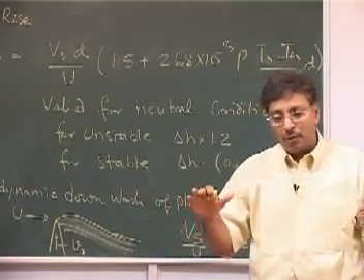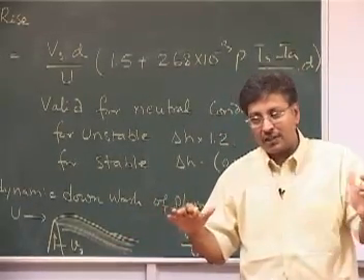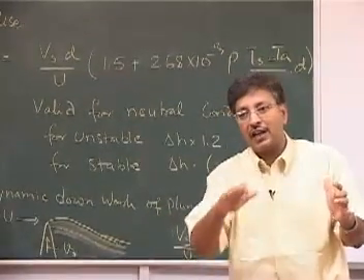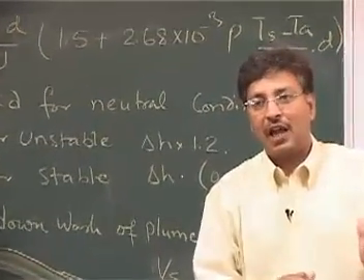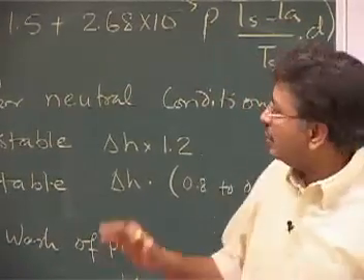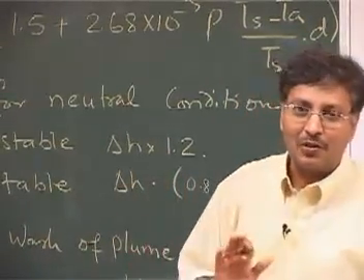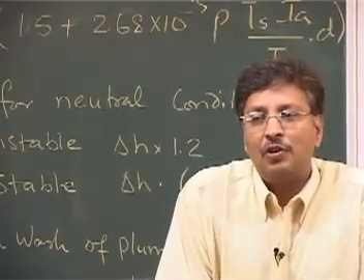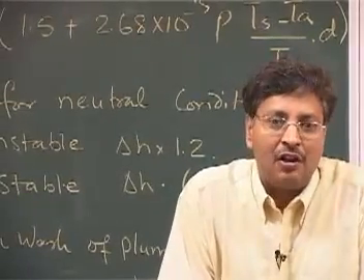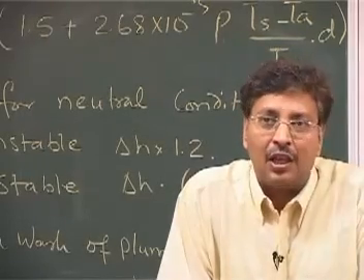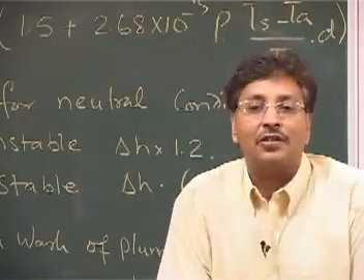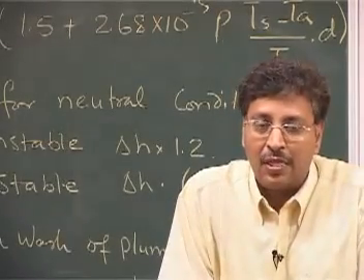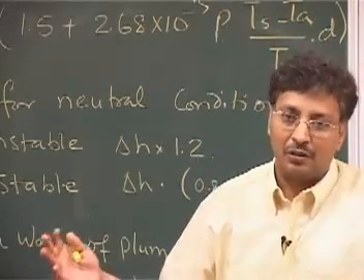So when the wind is coming from the sea side, the mixing height is governed more by the mixing height at the water level, and that has some changes. So generally what we are saying is valid for a source which is about 10 to 15 kilometers away from a water body. But as an approximation, as a tool to take some decision, this formula is still quite valid.